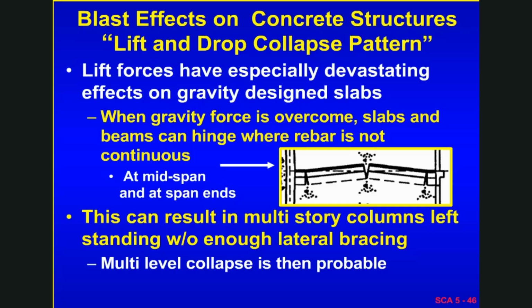But in the case of a blast, force is upward, which causes tension stresses to occur in the structure where there perhaps is not any reinforcement unless the structure has been designed for blast. And so you get this devastating effect of the structure sort of bending upward, cracking at the bottom near the ends, cracking in the middle near the top, and the structure then gets lifted up, and then it collapses to the lowest level.